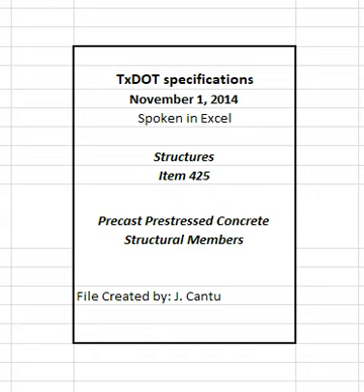Fit mating surfaces to prevent excessive grout leakage when erecting precast prestressed concrete bridge deck panels. Fill the joint with grout or seal it with an acceptable caulking compound before placing the cast-in-place portion of the slab if such fit is not provided.